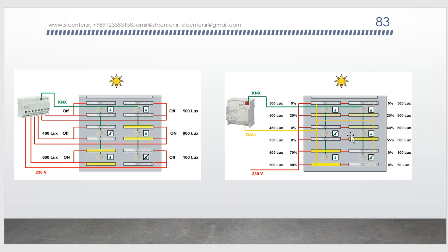It can be linear, daisy chain, star or tree, and then power up the Dali driver with the city power, and you have the different dims. Also, you can use the presence sensor from KNX and connect it to the KNX line. It's much better than here, where from each consumer you should have wiring to the actuators. This is much better.